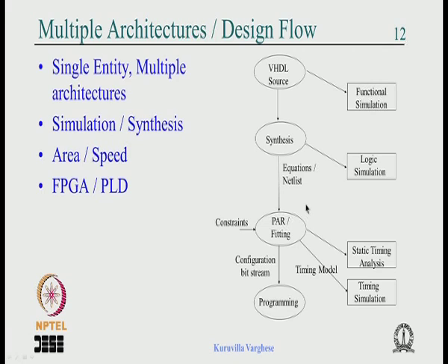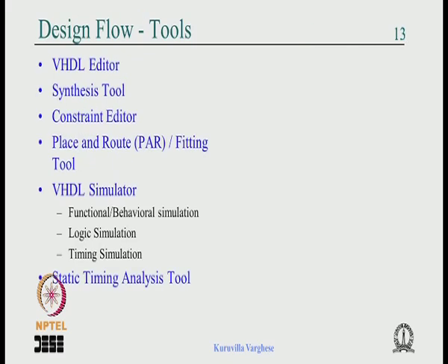It will be good if whatever is commonly used for a project can be in script form and you run the script and it writes output to various files. Maybe at the end of 6 hours, 8 hours or a day, you can check the various outputs and see how it goes. So that's the design methodology. As I said, it uses an editor, synthesis tool, constraint editor, place and route or fitting tool, a VHDL simulator which can do all these, and a static timing analysis tool. So that is the design methodology.